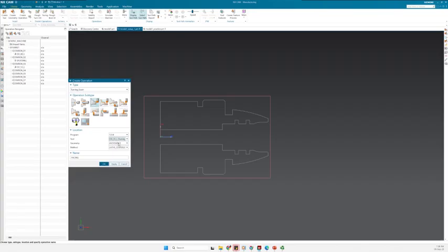The vocabulary that we need to use for the geometry is the avoidance. So simple, most of the operations are defined in the avoidance, and in avoidance, it basically means the tool part, the part component. But then we have the containment. The containment is the one where there is a risk of colliding with the spindle. Otherwise, most of them are avoidance, but it's anyway better to pay attention because this is the source of a lot of errors and mistakes of students. Then you can double check that one to make sure that you are defining the operation correctly.